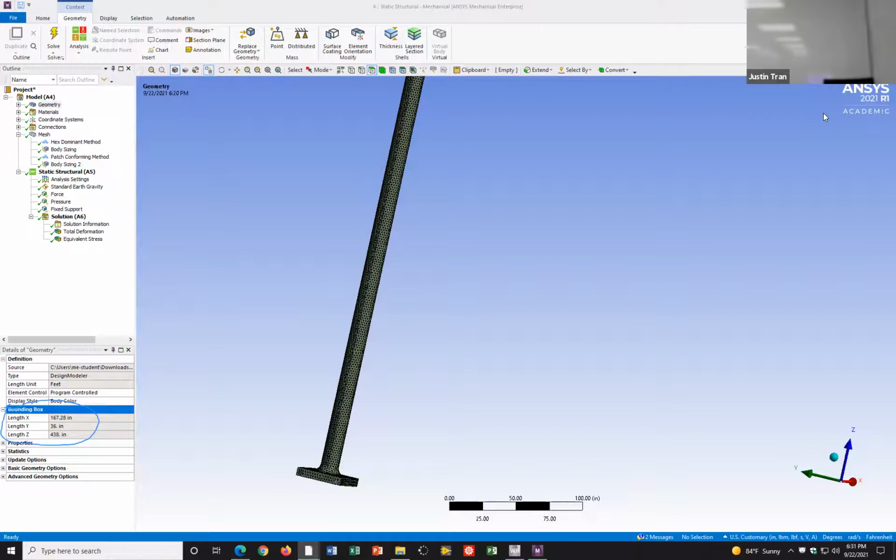What I like to do sometimes is just do the basic mesh settings first. I'll give it a run, and then if I see a place where I got some stress concentration, then I'll refine it. That's fine. One more thing: where can I check the skewness? Oh yes, that's true. We talked about that, right.